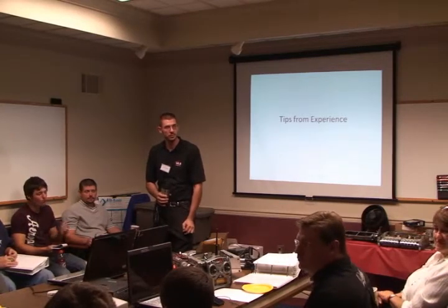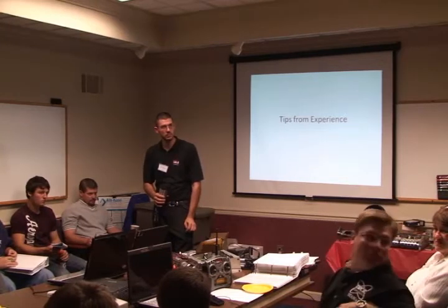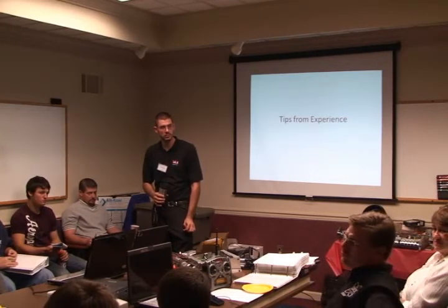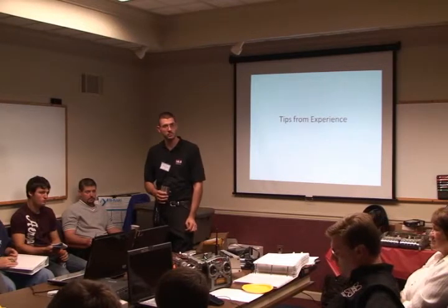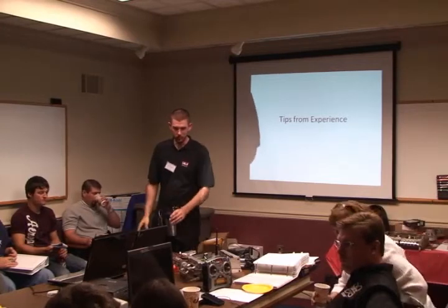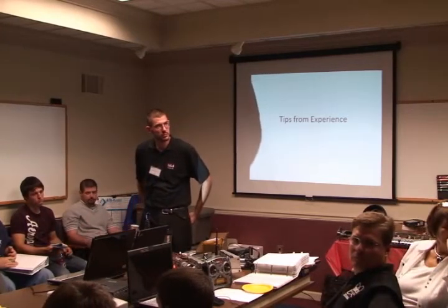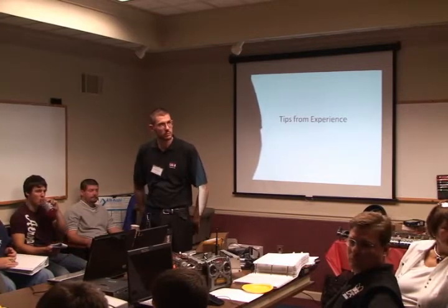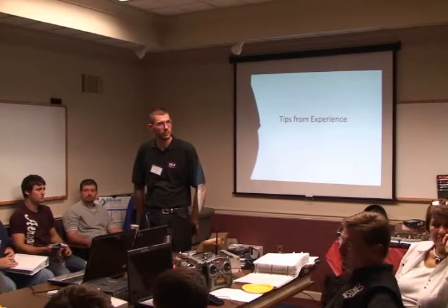And the other thing about driving too, most motors that you're going to use, whenever you first get them, they need to be broken in. You can't take a fresh motor and throw it right into a battle. It'll wear the contacts out a lot quicker. We went to a lot of different competitions, and you've seen teams running their batteries down for 2 hours, with the motor constantly running at a certain speed for 2 hours just to break in their contacts. And that's something that you want to do. You want to break your motors in. It's the best way to do it.